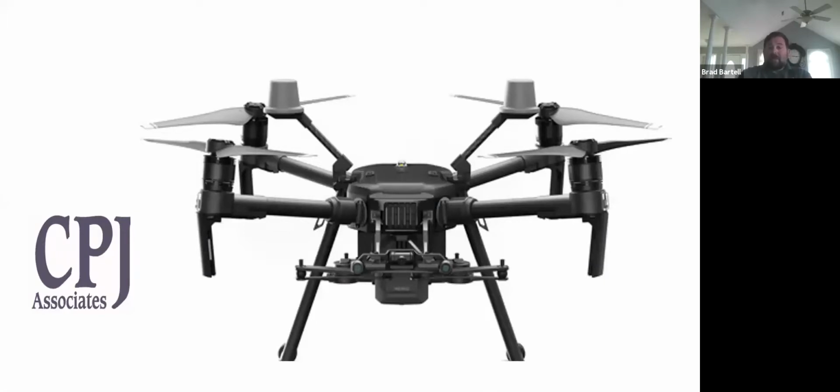The misconception with a lot of the LiDAR that the guys are going to fly here is that you need to be high. You can't really fly it that high because you're missing a lot of data. It blends out stuff. So I found that flying any of the LiDAR stuff, you want to be under 300 feet. Now, if trees are involved, you're going to have some problems anyway. We're trying to get coverage, and it's going to be on the ground. It really doesn't do that well unless you're talking around this time of year when the leaves are falling down. So we'll put that in perspective now. Drones in the woods, if it's a heavy canopy, you're not getting through. Now, with vegetation, such as wetlands and stuff like that, you'll see they'll start working into those.